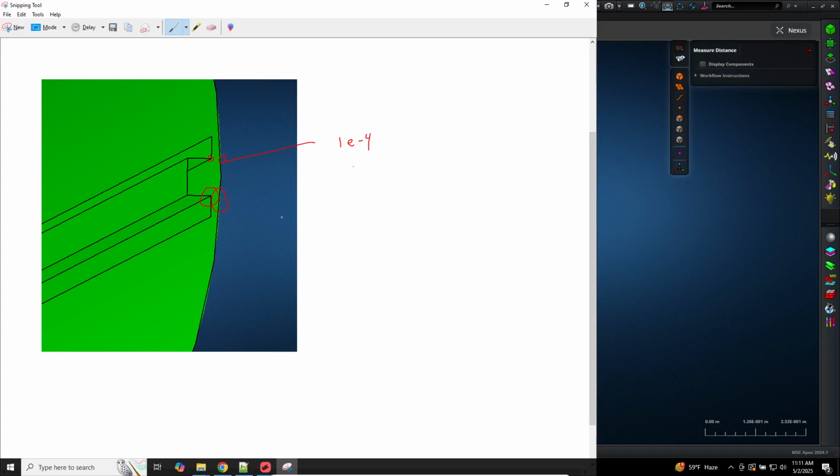It's not exactly spheres, but this is one of the best ways I have of explaining the contact detection distance. So imagine we have 2 spheres here and here. This is 0.02 meters. When you do this, guess what? The spheres overlap. So contact is detected.